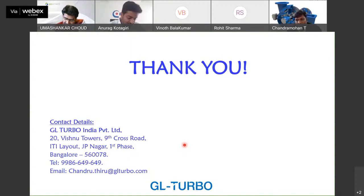And you have highlighted the hybrid technology and VFD also. You have highlighted 35 to 105%. Can we go up to 120% also for the utilization of VFD? Yes, it is possible. Then you'll have to slightly compensate on the lower side. So the turn down has to be a little higher, maybe 40 plus, then it would be possible.